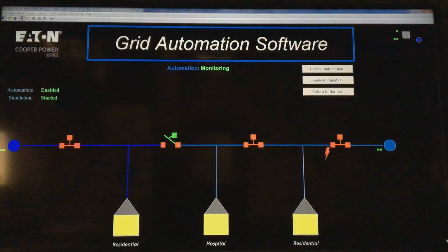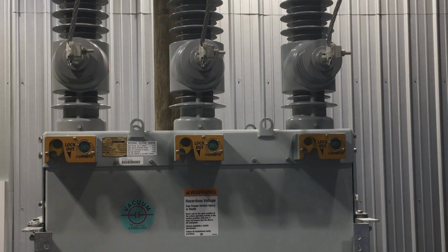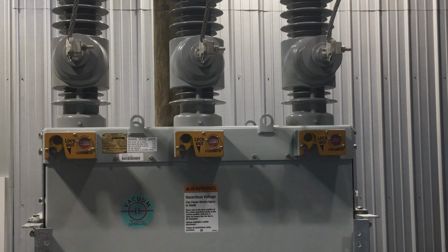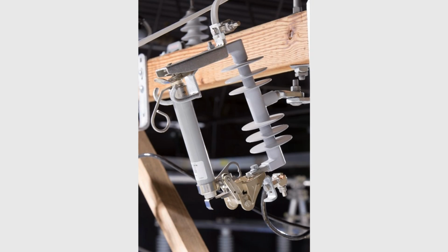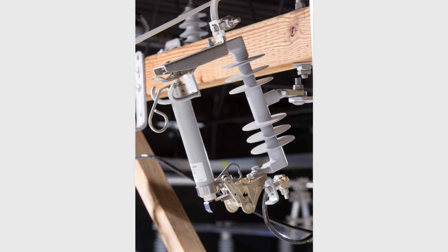Sometimes utility companies use reclosers at their substations and on their distribution feeders to clear temporary faults like lightning or tree contact. Then they reset the line after the temporary fault is cleared. By doing this, they don't have to send a utility truck and a lineman out to change a fuse cutout. However, if the fault's permanent, the fuse can blow and the system's coordinated.